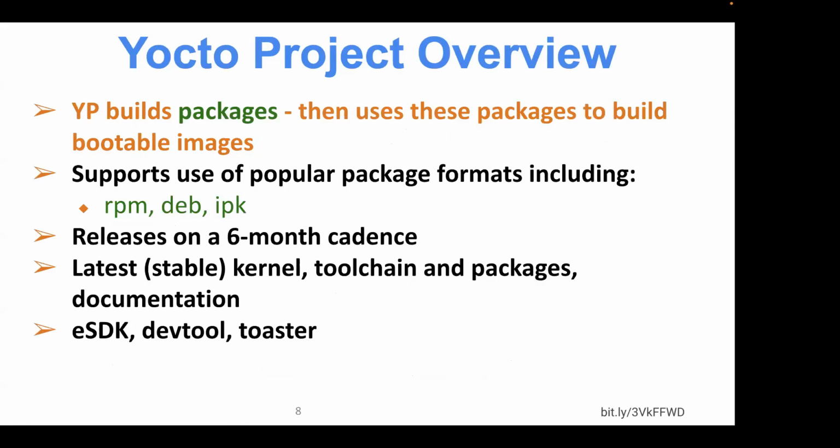Yeah, now Yocto Project is designed around the idea of building packages. And then from packages, we build bootable images. Now, this is a little bit different than a lot of other build systems. A lot of other build systems essentially use something like make. They build the binaries, the various files that are built, and then you install them into the place that you want them placed, and copy the directory that you make from the install onto your embedded target, and away you go.